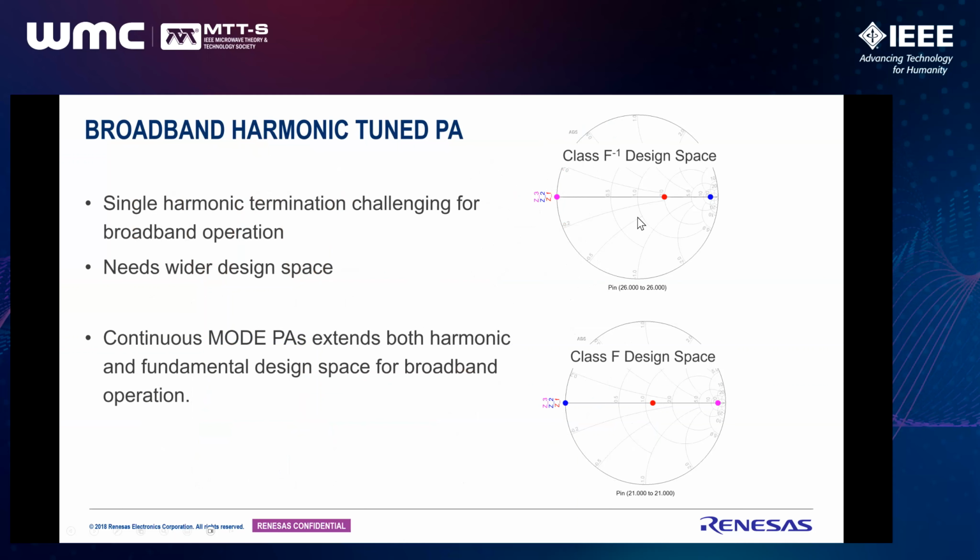So since there was no room for current peaking going beyond Imax, but for a GaN device, typically the device breakdown voltage is more than 3 VDD or even more, there was room to start peaking from the 2 VDD to more towards left and right. So there is room to shape the voltage higher than 2 VDD, and that's why it was chosen to introduce reactive components into the voltage to have a broader design space.